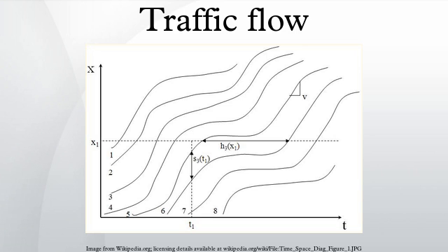For this example, consider 3 lanes of traffic in one direction. Assume that a truck starts traveling at speed v, slower than the free flow speed Vf. As shown on the fundamental diagram below, Q represents the reduced capacity around the truck. State A represents normal approaching traffic flow, again at speed Vf.